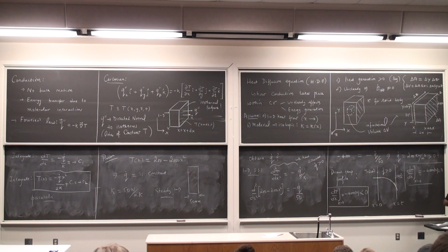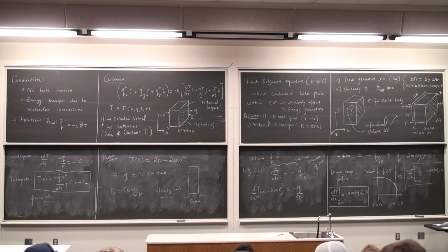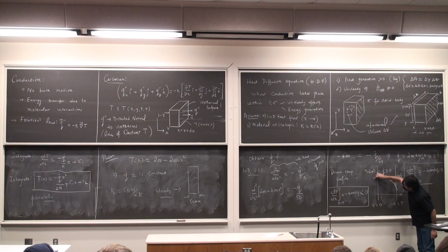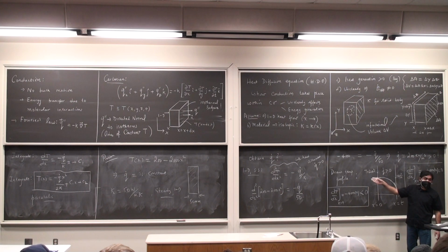So I obviously know the direction of heat transfer is from left to right, and I have to draw the temperature profile, which tells me exactly what I need to know. At each and every point, starting from a zero slope, which means that this is an adiabatic boundary, there is no energy transfer taking place at the left side of the wall.